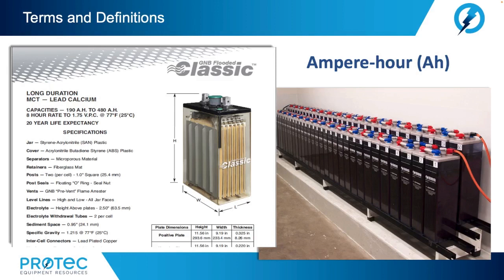Now as an example, let's say that we had a model number MCT2-4000. Well, based on this model number, it will provide 500 amps for 8 hours, or 500 amps times 8 would be the 4,000 amp hours that we see in the battery's model number.